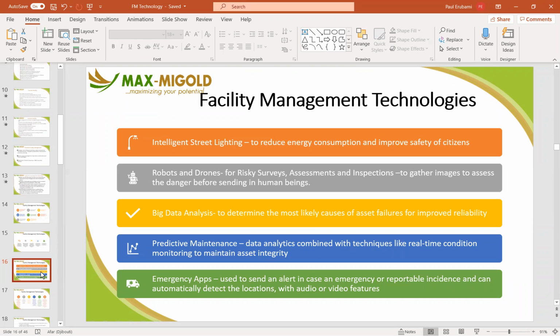So if I know the best case scenario is 6 to 7 months, worst case scenario is 1 year for the bulbs I used to use, before 6 months, while all the bulbs are still okay, based on my data and my reality, I take out all the bulbs, I use them elsewhere, and put new bulbs in. So I can have a continuous stream of SLA compliance without breaking the bank or getting into trouble.